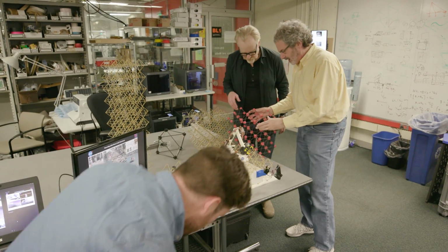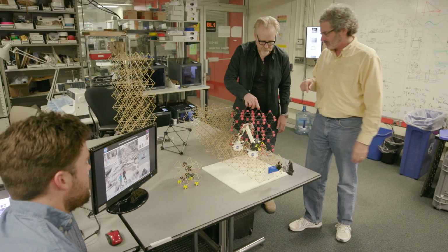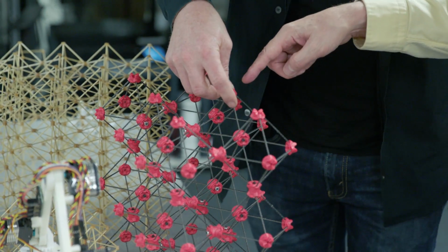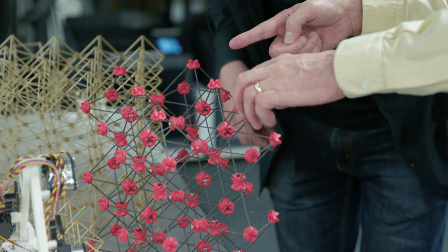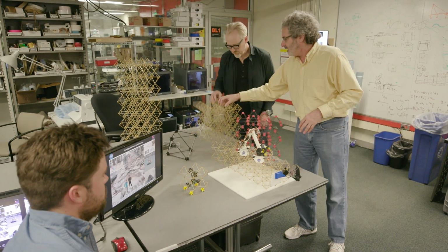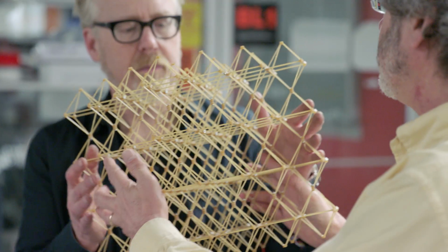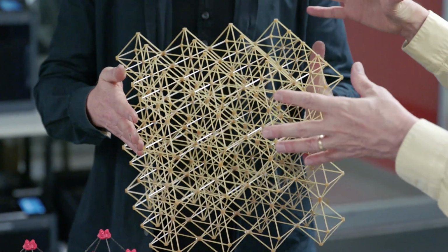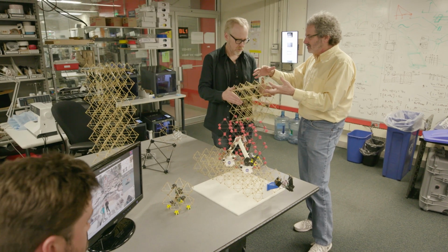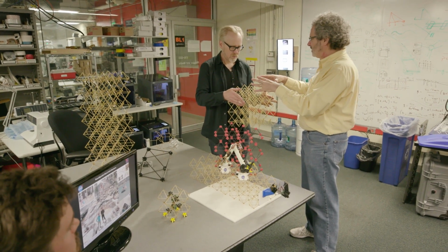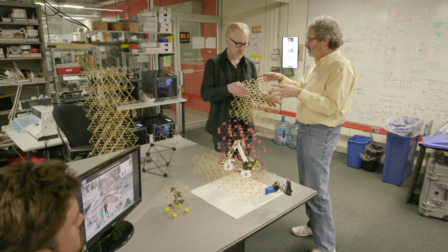Kenny in his thesis showed if you take loops of carbon fiber and you link them, here, push down on that. Whoa. Wow. So Kenny showed by making loops of carbon fiber, by an order of magnitude, it's the world's highest modulus ultralight material. So it behaves like a bulk material, much lighter than anything else, but it's completely reversibly constructed. So it's just like the Lego. The geometry is local, you can assemble and disassemble, but now it's to make aerostructures and space structures.